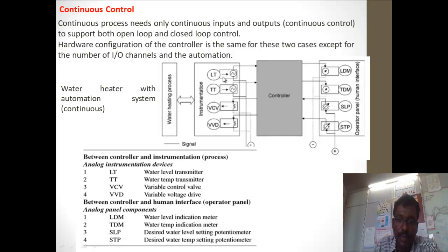Okay. So with respect to variable voltage, 0 to 2 volts indicates the temperature is low, which means we want to switch on the breaker and the heating coil in the element is going to be heated. If not, if the temperature is right, it can be set by the 3 to 5 volts. Like that, we can control the variable voltage source. The variable voltage takes care of controlling this process.